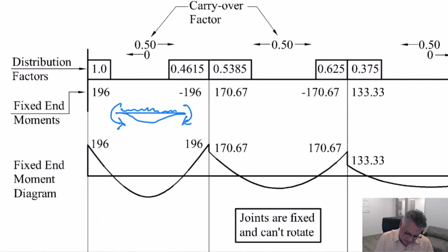Take your right hand, and we have got to hold this beam from rotating. So your right hand is creating that counterclockwise moment, and your thumb's coming at you. So your thumb is a big part of this. Hopefully you have opposable thumbs like I do. This tells you it's positive. Your thumb is coming up at you. This is numerically going to be a positive number. That's why that is positive.